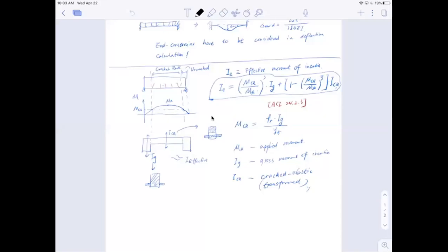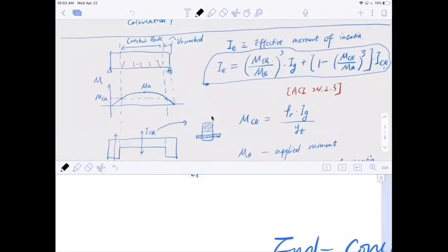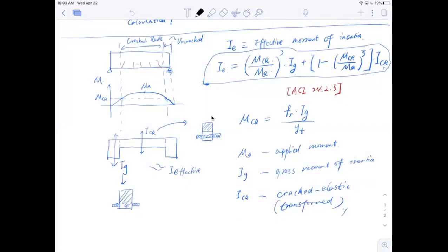All right. So one more thing, some of the students have brought up this minimum reinforcement area on the one-way slab. Specifically, if you go back to the ACI code, the one-way slab is in Chapter 7. The minimum reinforcement is mentioned in 7.6.1, and the number is slightly lower, which is 0.0018, instead of the 0.002 that we talked about.